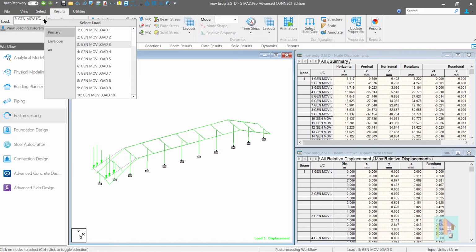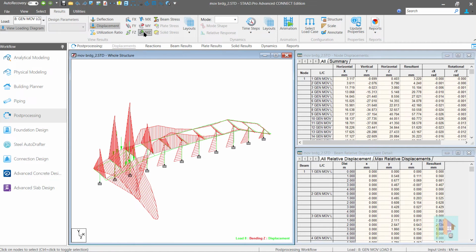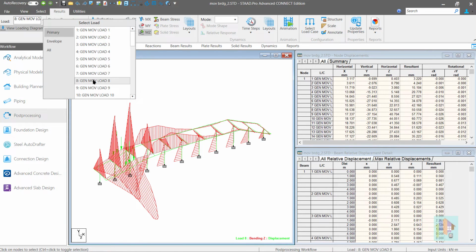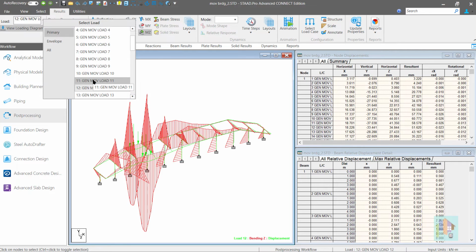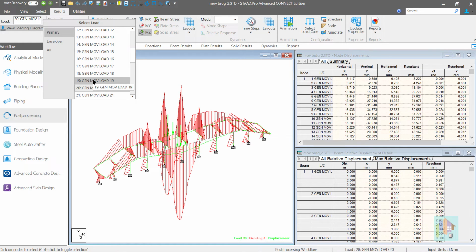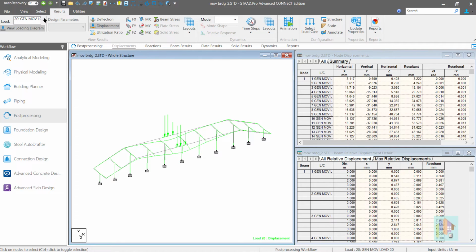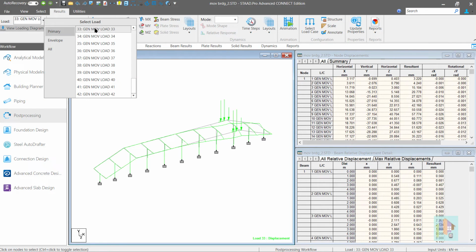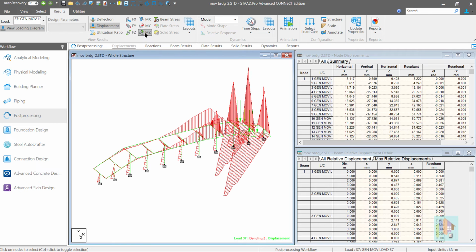As the load moves along this structure, moment and deflection profiles change, and it not only affects the loaded bay, the entire structure is affected due to the load transfer mechanism. This might not be true for a bridge deck with expansion joint and bearing support, but for a continuous crane girder, this is very common. For this entire movement of the load, there are a few application points which generate the maximum bending moment or deflection, and these positions are required to design the structure properly for strength and serviceability conditions.